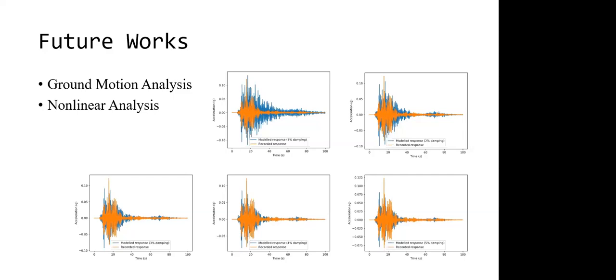Yeah. Well, to be honest, I'm making a building model, and the thing with my code is that I want it to be scalable, meaning that if I extend the number of bays or if I increase the number of stories, then I just have to change 1 or 2 variables, and it will do that on its own. That's why it's taking me quite a while. Simply forming my elements and then adding the zero length elements and all that takes a while. So I have an illustration of how my grids look like, so that it's easier for me to understand what's going on, because sometimes it gets a little bit difficult.